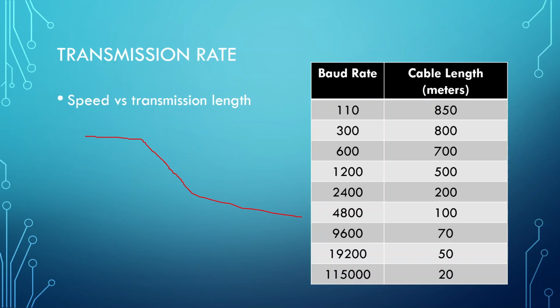And capacitors store energy. So if at one moment I'm telling you, here's 25 volts, and the next moment I'm telling you, here's negative 25 volts, it's like, hold on, I've got to drain my voltage down. Like, let me dump the pitcher out. The longer the wire is, the smaller the hole that you're dumping that water in. So it takes time to discharge and recharge that capacitor in another direction. That's why the length of the wire matters. By keeping the wire shorter, we have a smaller capacitance, which means we can transition faster.